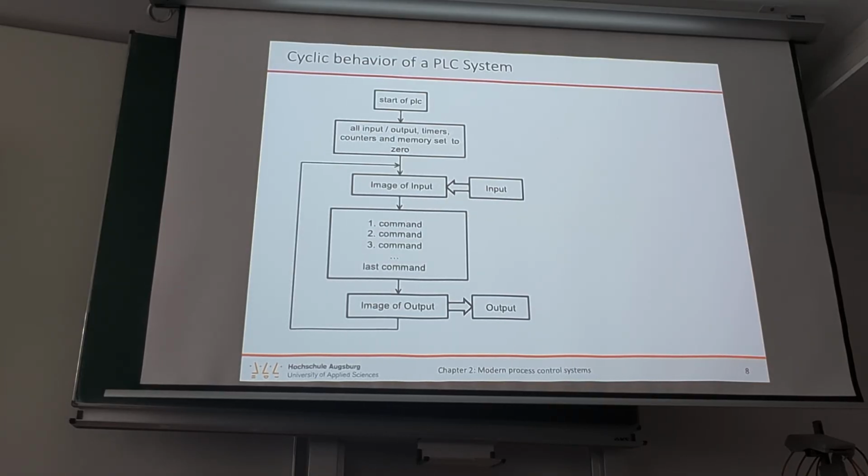The reason is it makes it possible to do online changes, and then with the next cycle start with a new program. Because in the microcontroller, if you work on IOs and it's always slightly off by the timing, you don't actually know when to start with the next cycle. It makes life harder there to change the firmware on the fly.